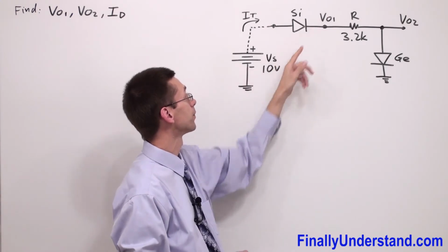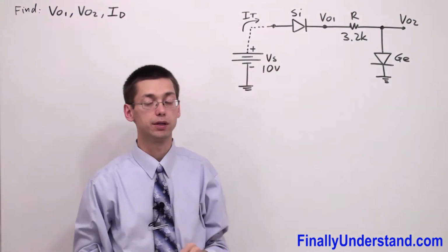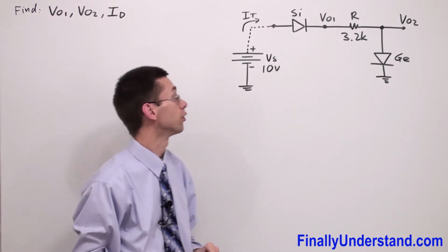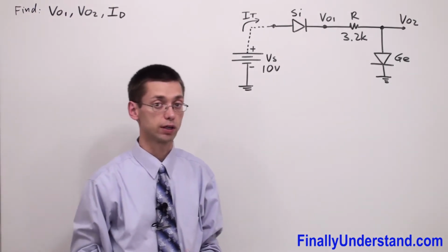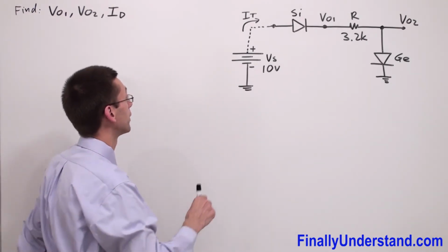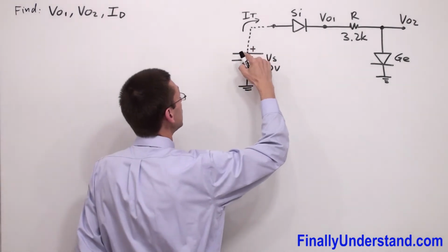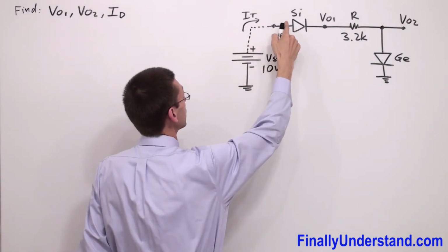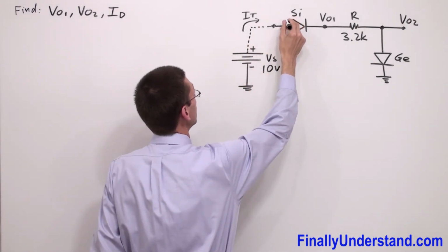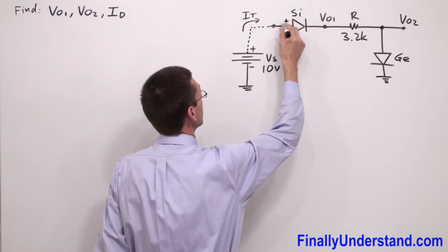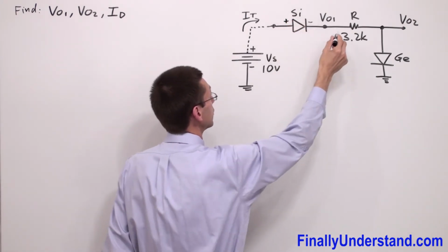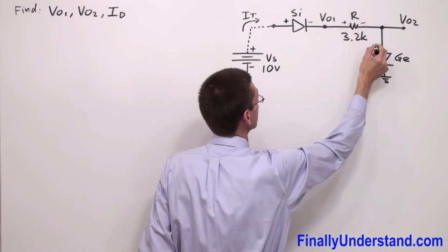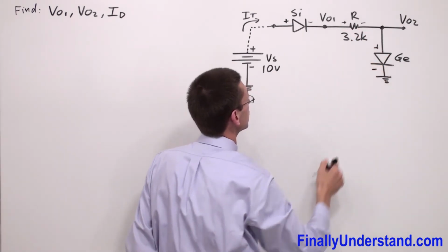So it means that we can determine the output voltage 1 without any extra calculations. What I mean by that? Remember that anytime current is going to enter any component, we're supposed to put a positive sign. Anytime current is leaving, we're supposed to put negative. We have positive, negative, and I have positive, negative.